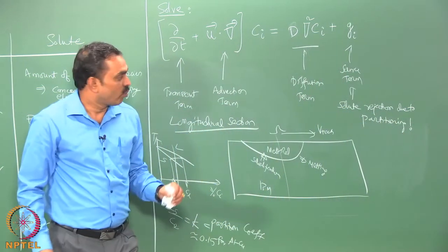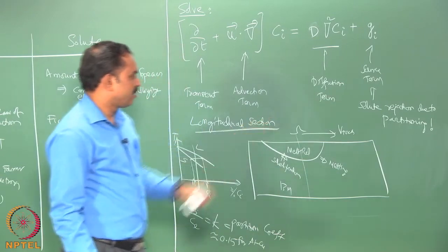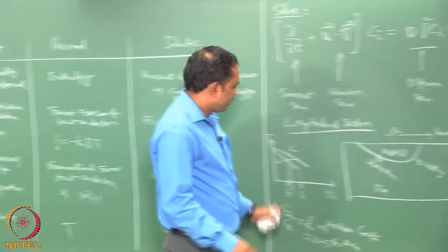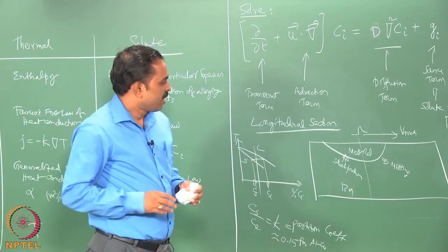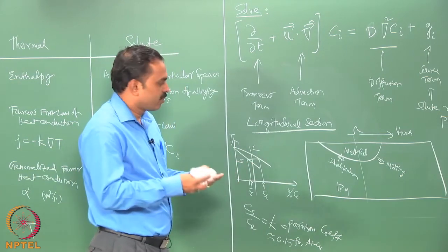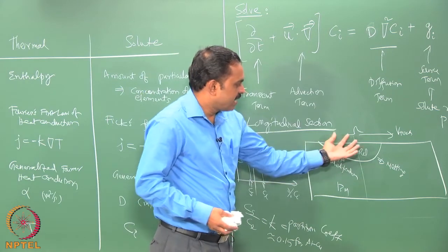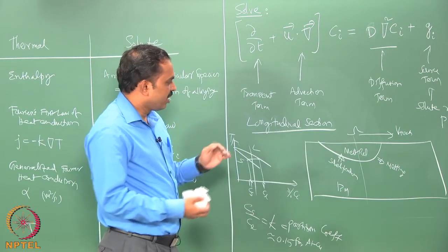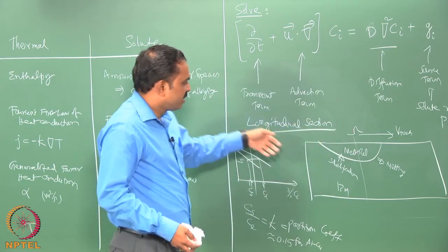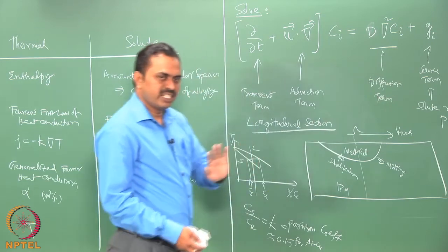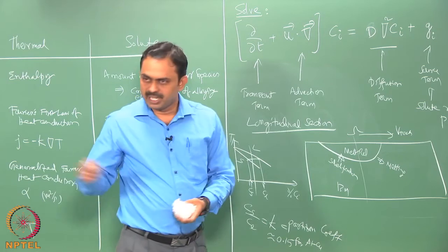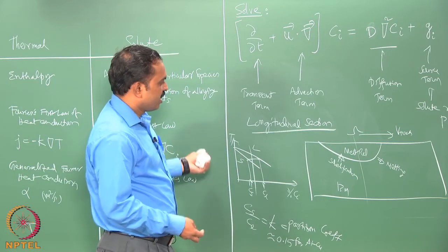and there are reasons why we normally can ignore that, because we have noticed that the scale at which the partitioning is happening is so small that it could be absorbed within the variations of the microstructure that is possible in the solid as it is growing. So, that at the system scale really not much of flux is getting dumped into the melt pool. In other words, the melt pool as it moves along, the concentration does not change with time, because there are reasons to believe that, and that will be evident after we complete the microscale model of this particular solute transfer.